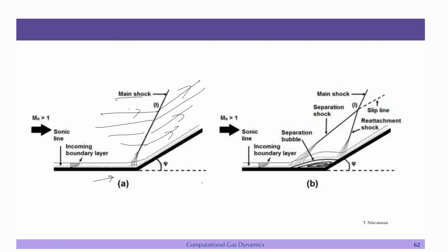In the boundary layer, however, when you introduce viscosity, the flow speed goes to a very small value, and there is a viscous sublayer, or let me call it a region where the viscosity is dominant. In that region the information can go upstream.